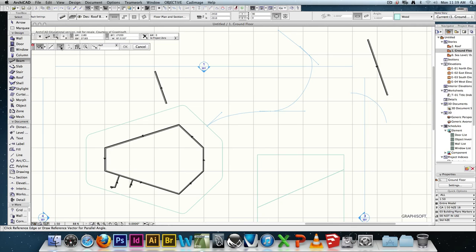Now, these things are available whenever you like as well. So if you're in the middle of drawing a big poly wall, and you need this to come back and hit this at 90 degrees, but don't actually want to join the wall, 90 degrees to that one. Boom. Cool. Okay, how about parallel? Exactly the same sort of thing. I'm in the middle of drawing. I need this to be parallel to this. Yes, I could hover over it and eventually I'll get a little parallel line. Or I could pop up here, say parallel, which is the next option, to this. And now I know that that there is running parallel to that there. Awesome.